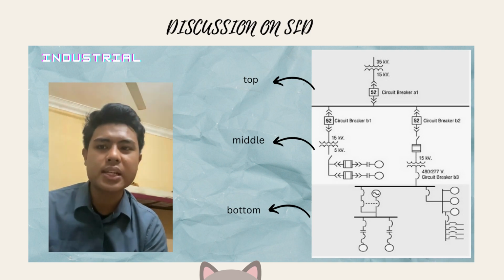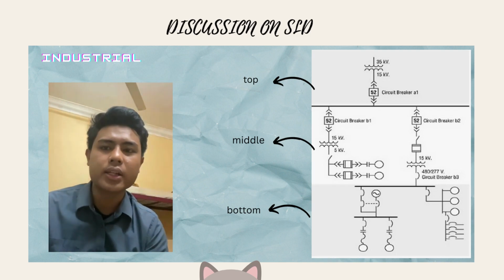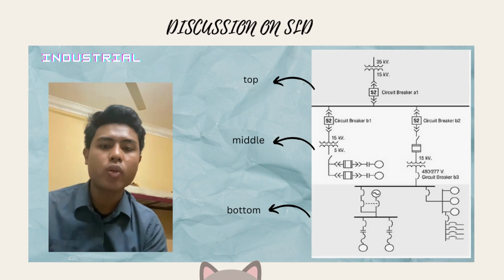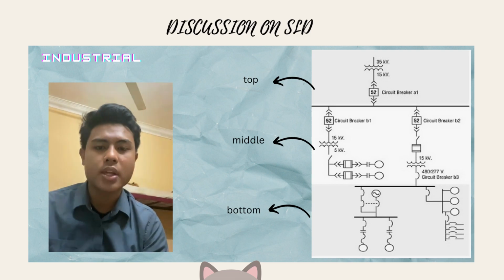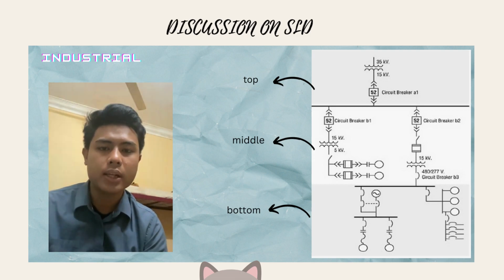You can see from the single line graphic that if the power goes out, the automatic transfer switch would link the emergency generator into the circuit to keep the equipment working. Therefore, they keep the machinery operating. That's all from me for the single line diagram in industrial.